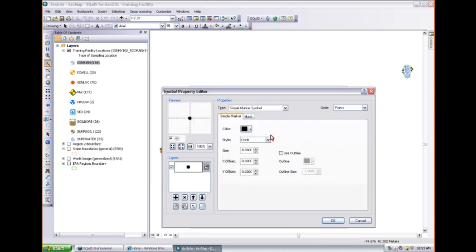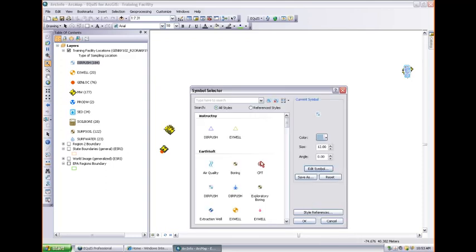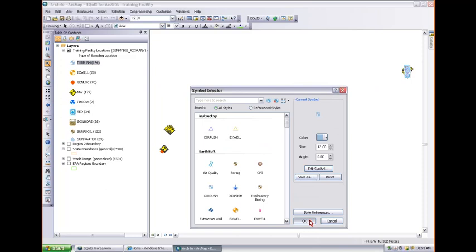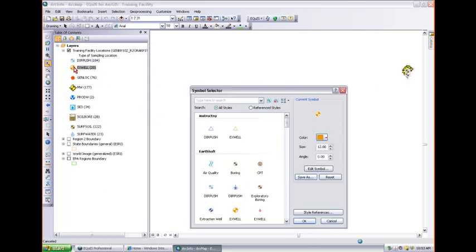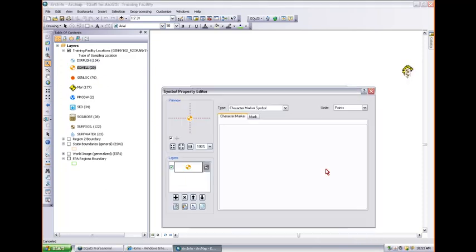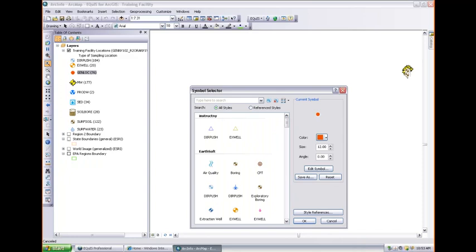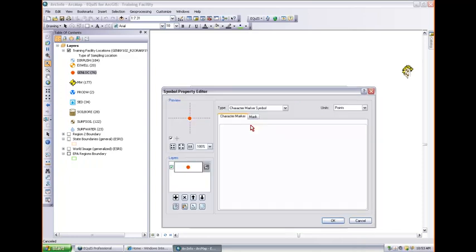We can use something they call a simple marker symbol. That's just like circles, squares, diamonds. But also, just removing that halo, as they call it, can help. So let's try removing the halo, because 666 is not that many locations, actually. So we'll take off the halo. I know I'm going fast, but this is standard ArcGIS symbology. This has nothing to do with EQuIS ArcGIS per se.